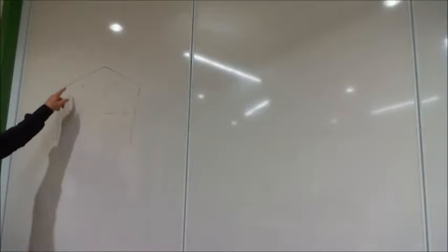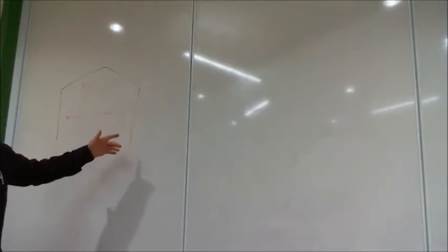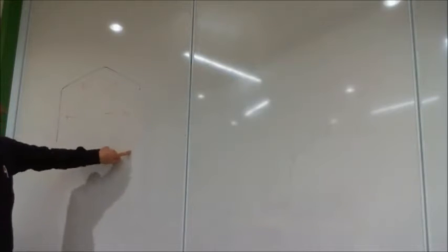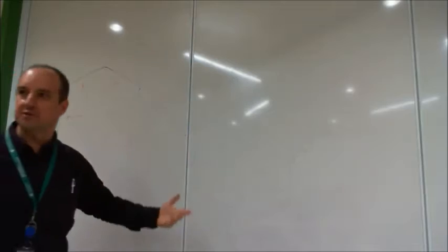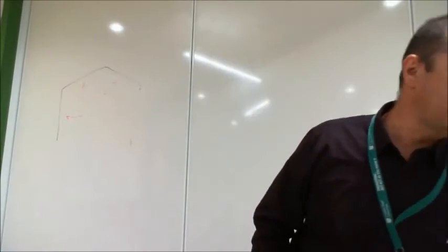And the internal pressure always acts equally on all the surfaces, where there is a surface. So if that's like an open shed, the internal pressure acts there, but not on that, because there's no surface to act on.